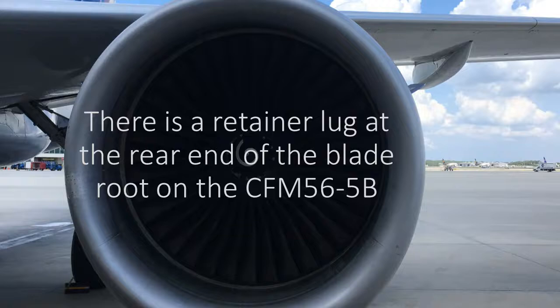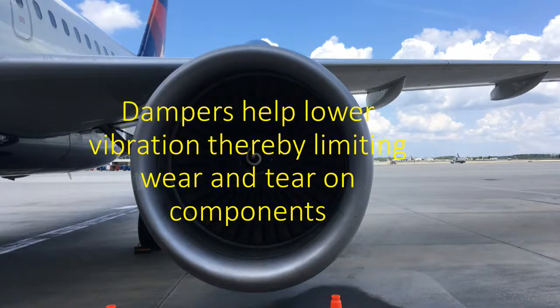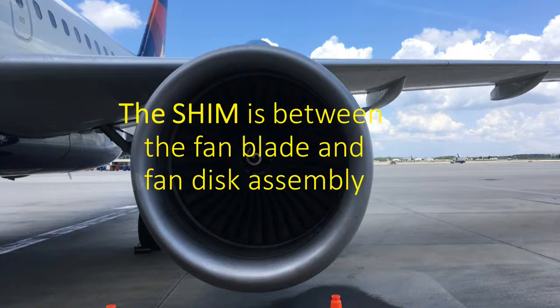The idea there is it's engaging that forward flange of the booster spool. Again, the idea here is it's limiting. The spacer and the retainer lug are creating a limitation of movement to some small degree. The other thing you'll find is dampers, right? Because we have a problem with vibration when things are moving, and if we can keep the vibration to a minimum, then we have less wear and tear of the components involved in the operations. Okay, I do want to mention the shim. There's a shim between the fan blade and the fan disc assembly. So just keep that in mind.